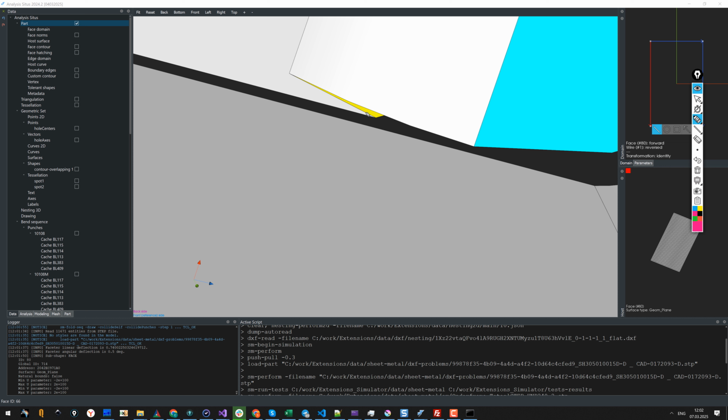And what this function does, it actually does a very simple thing. It takes the base face, what I just selected, it builds a prism with this highlighted face as a base face and the height of 0.3 in this case. And because I use a negative number, then instead of extending the prism in the positive direction, it takes the negative direction with respect to the material orientation.